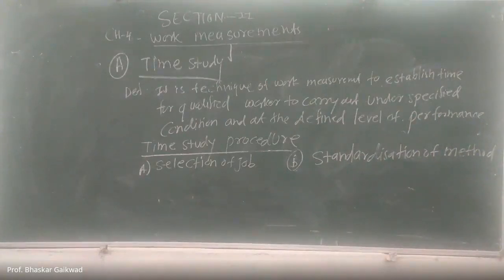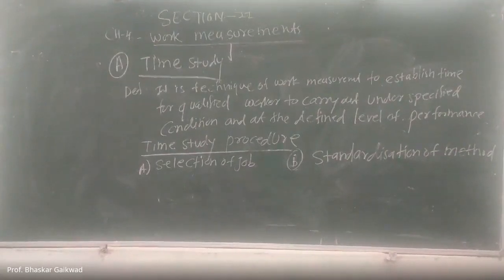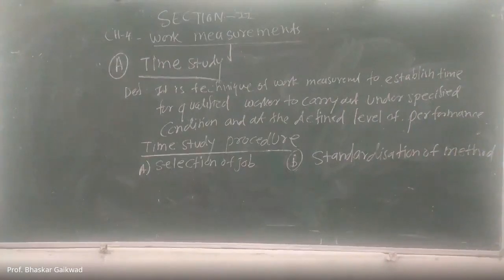Then we have to select such a job for time study, or we need to go for standardization. If there is no standardization, these fixtures are not there, a set method is not there, a machining problem is there and there is no standard method, then in order to make the standard, we require the time study.